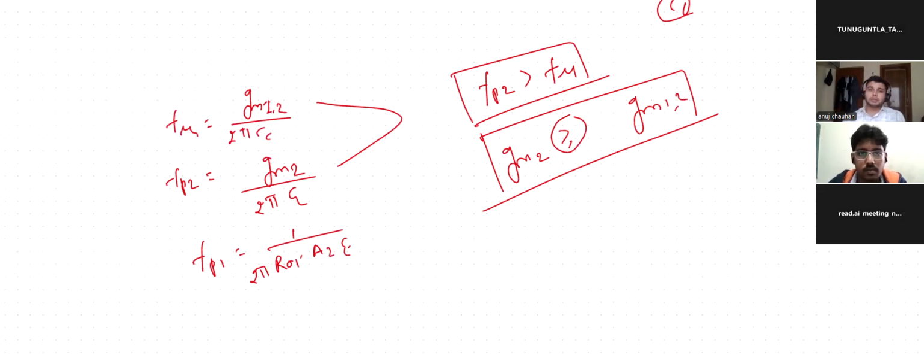But for better UGB, we also want the first stage GM to be more. It depends on what application you are using it for. If you want more GM from the first stage, we have to run more current in the first stage, or size the transistors strongly, or apart from strong inversion, sometimes size them in the sub-threshold region, so that we get more GM for a particular current, which is better for getting good UGB.